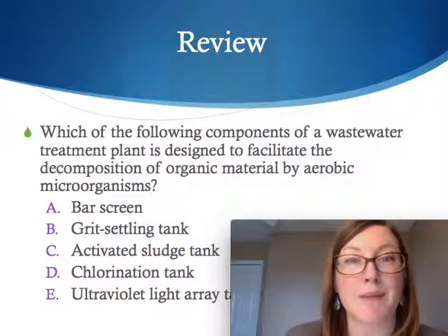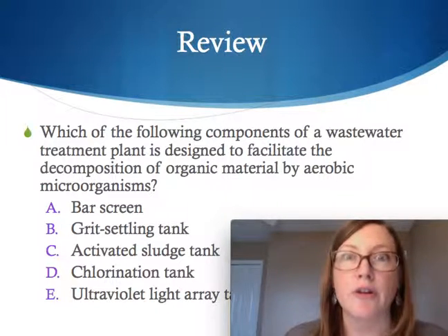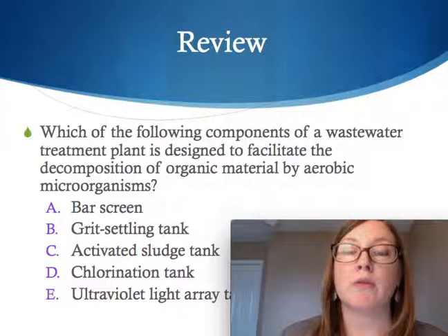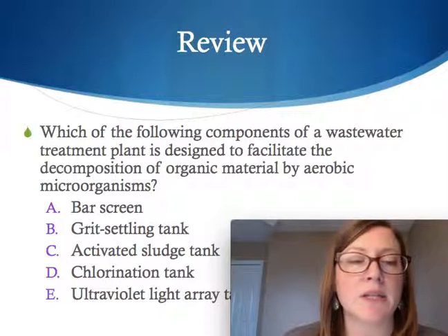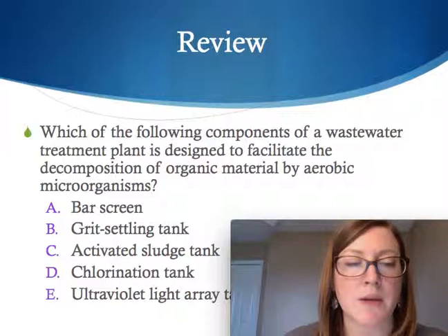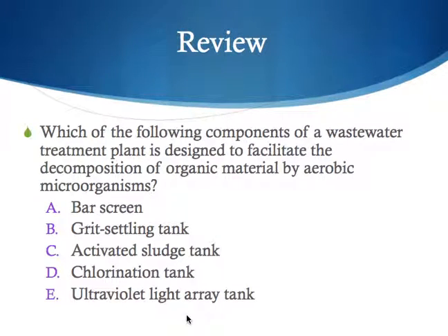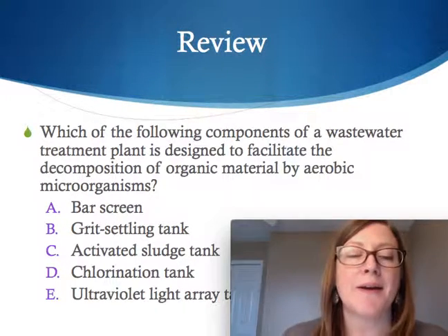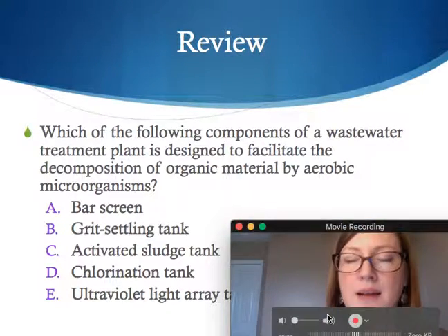That word aerobic made me think about oxygen, and I remember that secondary treatment is all about encouraging oxygen, because I want those microorganisms to digest that dissolved organic material. Bar screen and grit settling tank, that's not secondary. That happens in primary treatment. Activated sludge, yeah, I'm pretty sure that's it. Chlorination and UV light array tank, those are both involved in disinfection, so I'm picking C. That's got to be the right answer.